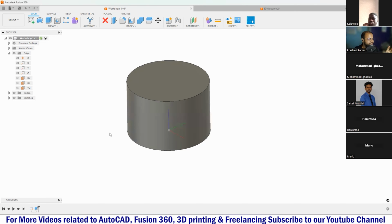It's a very basic shape, but still, the process we followed was that we created a basic sketch first, and then we used that basic sketch to create a 3D model. The two steps that we followed are also recorded at the bottom. Here you can see the first history item is the sketch, the second is the extrude operation that we just performed. So I think that is helpful up to this point.